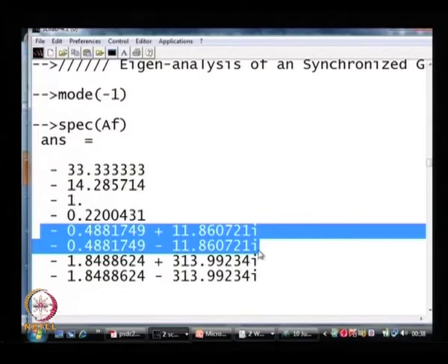If you take the classical model directly, just because there are two differential equations, you have just one mode, and that represents, as we have seen in the beginning where we analyzed this toy model, the electromechanical oscillation. So, the classical model is okay just to theoretically highlight the fact that you do have such a mode, which is mainly associated with the electromechanical variables delta and omega.